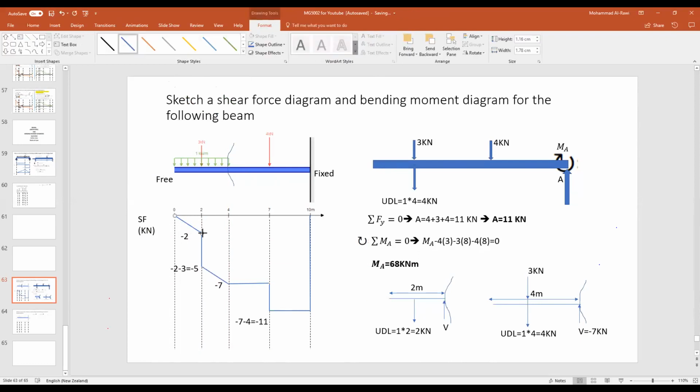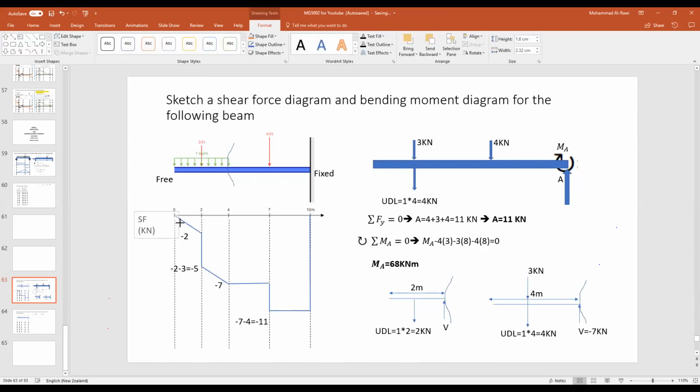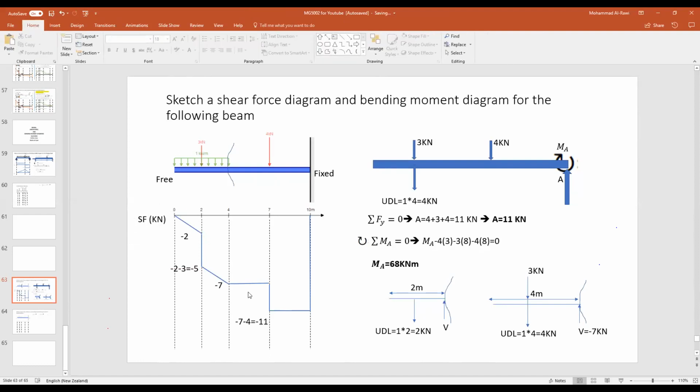I'll go by the time, okay? So that's how it should be, the shear force diagram. So again, please just correct this. Because we're drawing the shear force diagram, these values should all be correct except the shape. It should be converted to a slope or gradient going downwards. So let's see the comments now. I presume there are 3 comments. Why is it a curve? Yeah, okay, I got one saying why a curve, which was about 3 minutes ago.